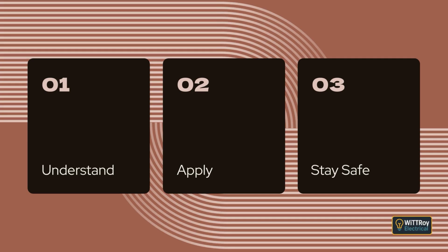Clause 3.11.4.4 Minimum depth of cover. Underground wiring must be buried to a depth suitable for the specific installation. The required depth depends on whether the wiring is inside a building, beneath poured concrete, or out in natural ground. The minimum depth is based on the top of the wiring system, or on the top of the mechanical protection layer if used.